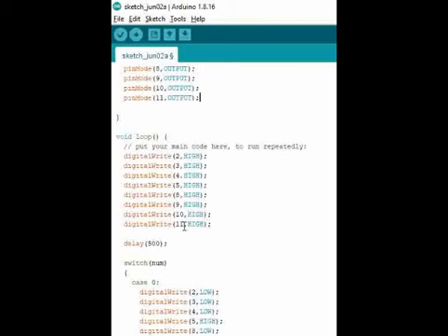So why we are setting all these pins to high is, initially when you power on, nothing should come up, right? There should not be any default state. I mean, default number display on the 7 segment display. All the pins should be in default states. Nothing should operate, and we should start from a known state. So that is why these are all set to high.